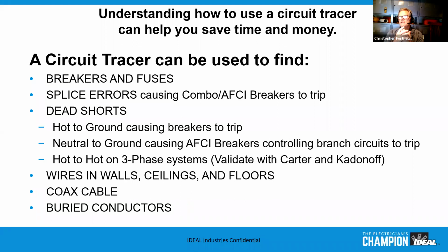So the bottom line is that understanding how to use a circuit tracer can help you save time and money, and it can be used to find breakers and fuses, splice errors, dead shorts, wires in walls, ceilings and floors, even coax, cable, and buried conductors to a certain extent. So we want to go through some of this with you today.